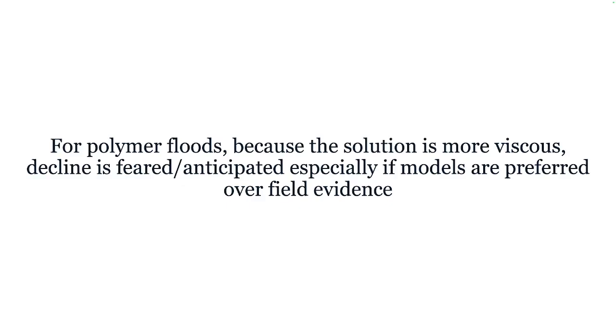For polymer floods, because the solution is more viscous, this is the main reason why people fear or anticipate differences with water injection, because the viscosity of water is low, even lower at high temperatures. With polymer, when you go from 1 centipoise to 5, 10, 20, 50, then of course it is normal to anticipate a change in reservoir response because of the viscosity.